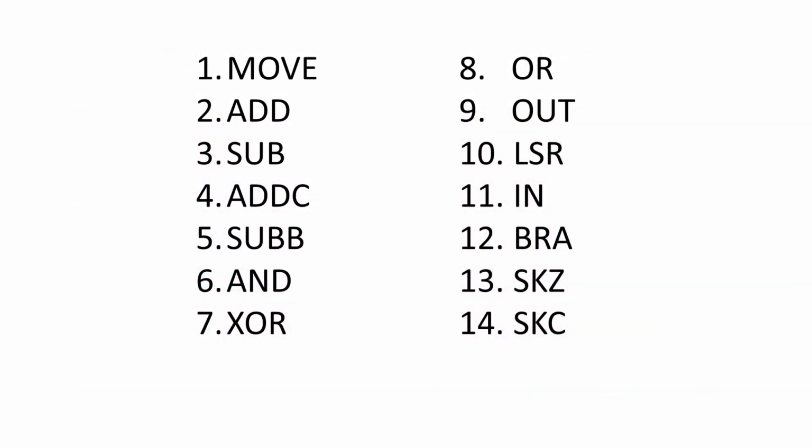Now these are the instructions. Move, which is move data from one place to another. Add, which means add one value to another. And there's subtract one value from the other. Then there's add with carry. This allows you to do 16-bit maths with an 8-bit processor. And there's sub with borrow, which again allows you to do 16-bit maths with an 8-bit processor.